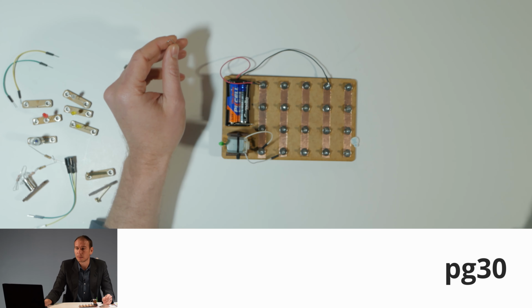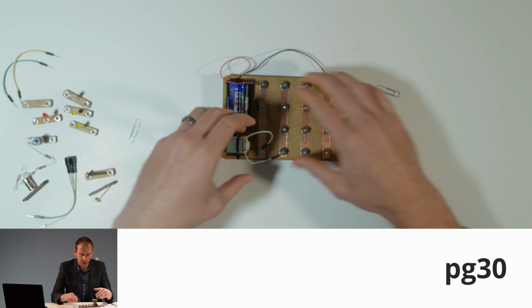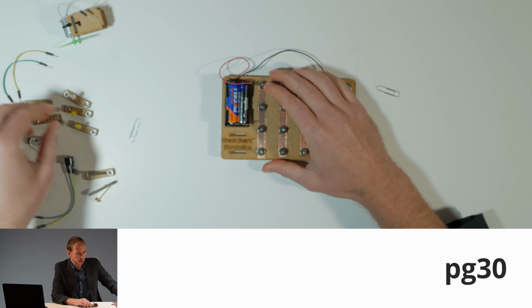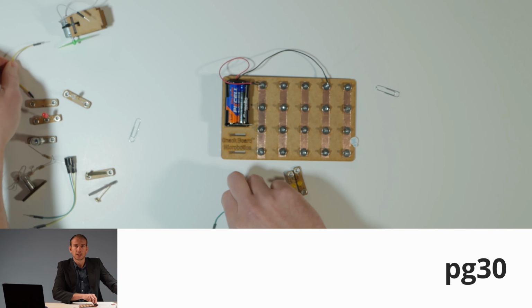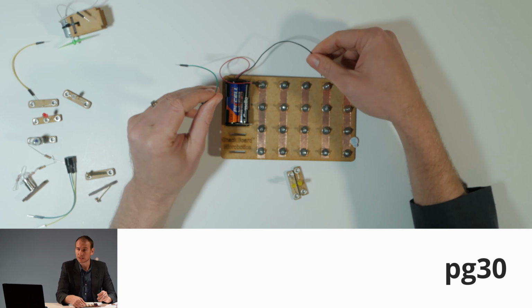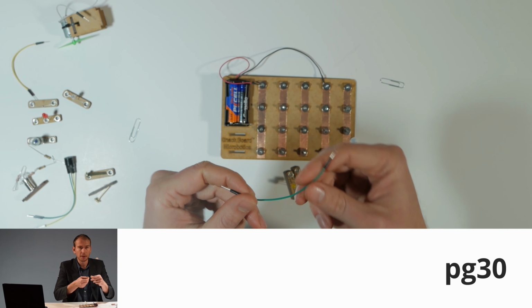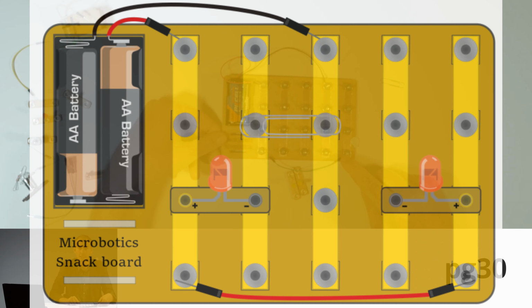Now quickly go to page 31, and at the top of page 31 we're going to make that circuit. Okay, so we need to remove our motor. We need to get our flashing LEDs. We'll need a male wire so that we can connect these 2 sides. I think the most important thing to notice is that the positive is on the left, and we use the male to male to extend the positive all the way to the right as well.